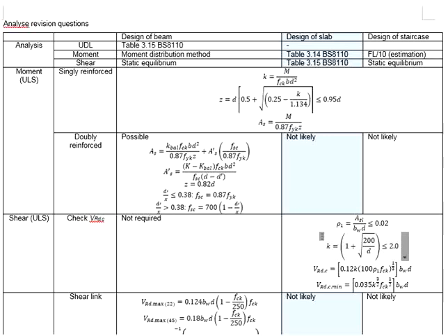Such a situation is similar to the design of one-way slab. One-way slab, we assume that the load is only transferred in one direction, which is at the shorter span. That means there will be moment in the shorter span only. As for the longer span, the analysis will end up without any moment.